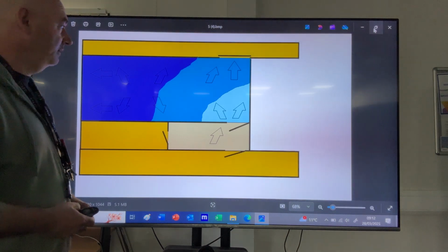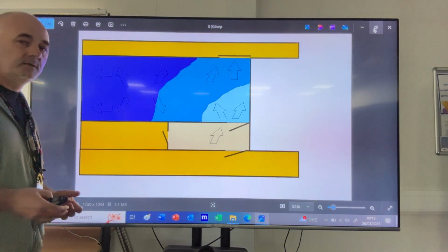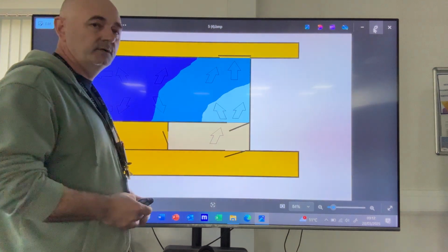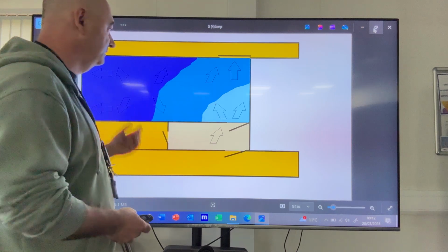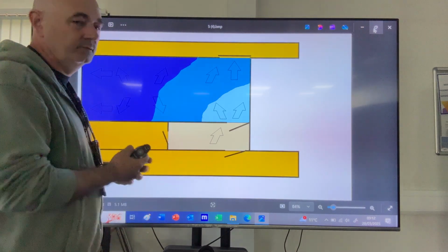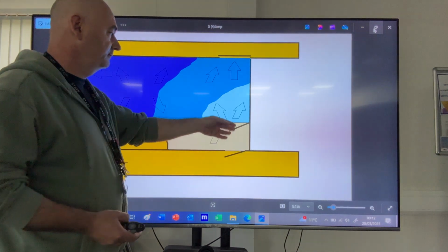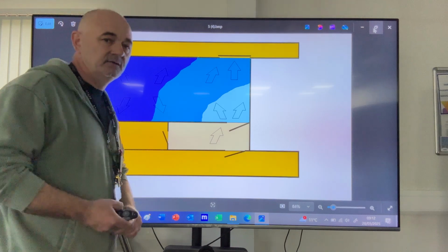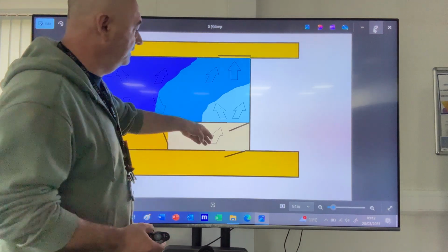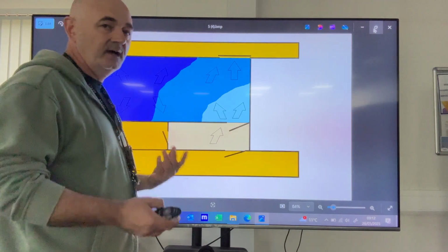Other problems: if we have only one sensor in a room, the validated documents probably should state that this is the highest corner of the room and is deemed to be the reference point for the entire room. Because when I checked room 323, near room 325, where the door is, I had about 16 degrees, while in the furthest corner I had 5 degrees, because I have air leak from 325 directly into this sensor, and I have false information.